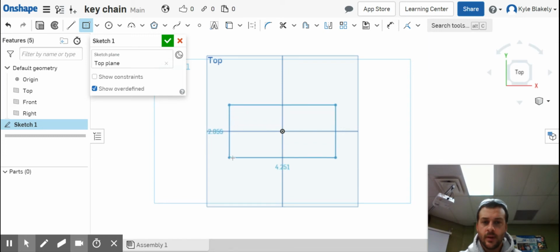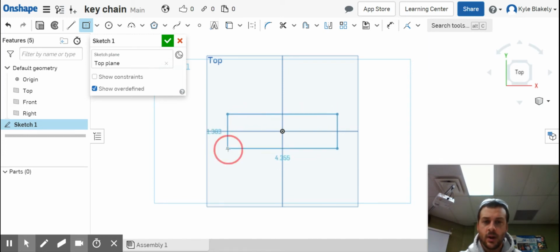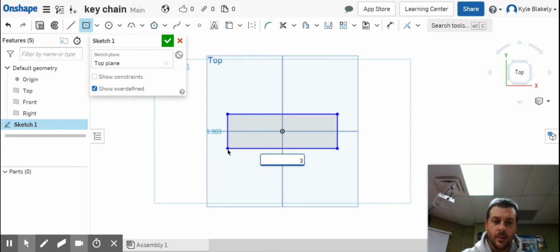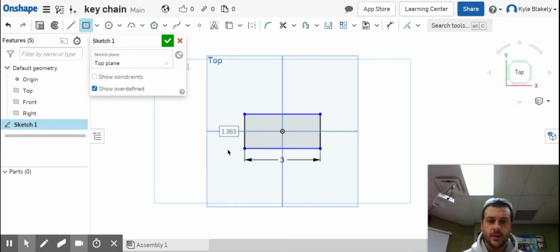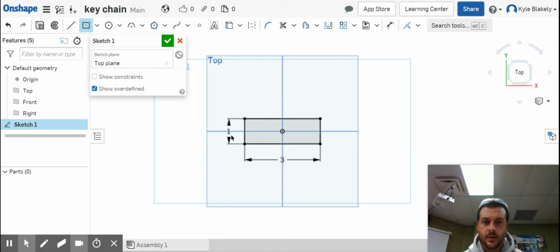So you can drag out and click once. You see the box highlights, you can type in the length. So we're going to make this 3 inches. Then hit enter, and it jumps over to the other box. When that highlights, type 1 inch. When I hit tab, it showed the IN pop in, so you know you're working in inches.